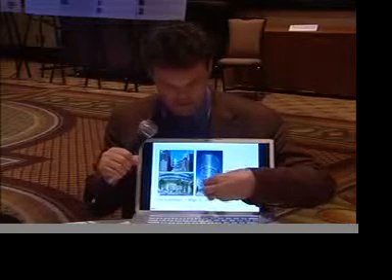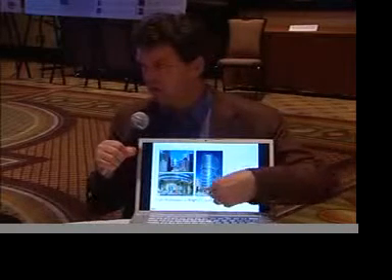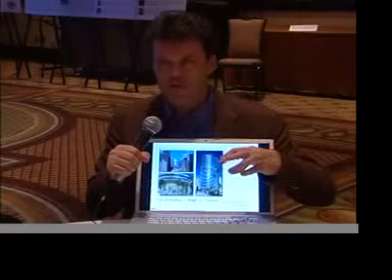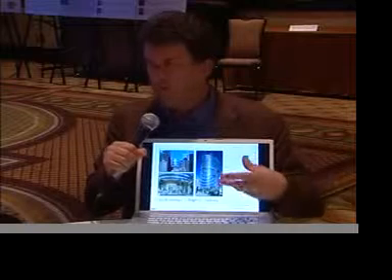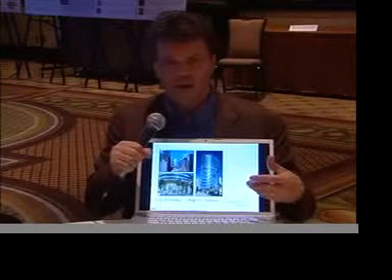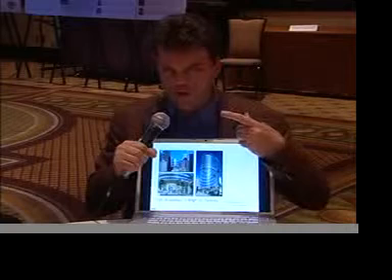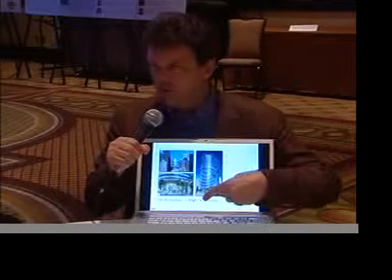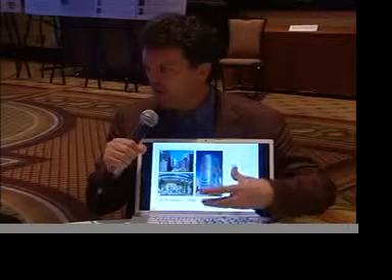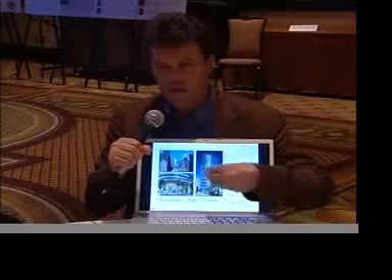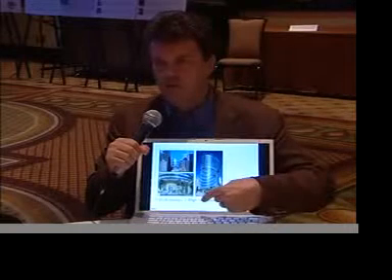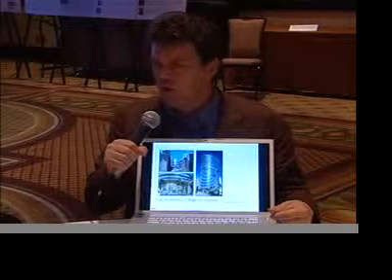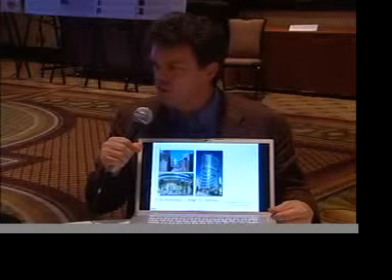We're taking water from the sewer that runs right by this building, because what we're seeing is a trend towards buildings becoming so efficient with fixtures that you can only generate enough wastewater from the building itself, especially in a commercial building where there's not much showering and no residents, to cover the toilet flush. But only a quarter of the building's use is toilet flushing; the other three quarters is cooling towers.